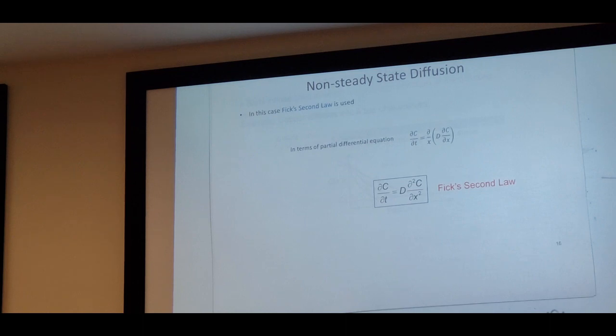So remember, in the solid phase, diffusion is a very slow process. In the gaseous phase, it's very fast. In the liquid phase, it is faster, not faster than gaseous, but faster than solids. But in solids, the diffusion is a very slow process. And this steady state can be reached only when you take an extremely thin sheet of palladium or whatever that medium is. But in most other cases, it is not steady state, it is non-steady state diffusion.